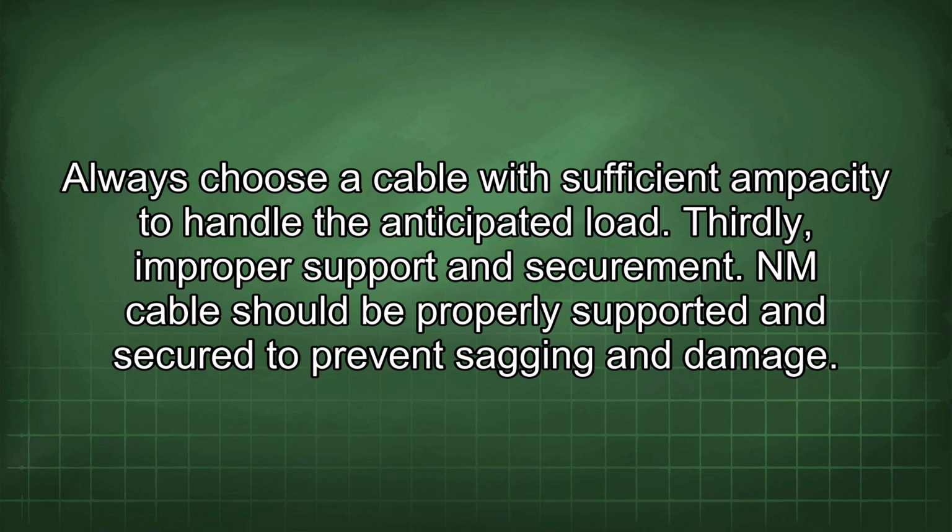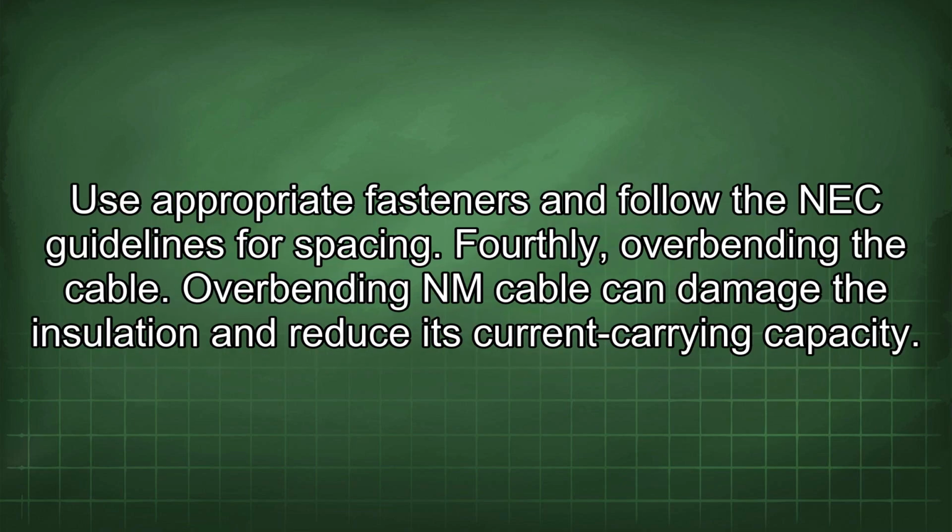Thirdly, improper support and securement. An NM cable should be properly supported and secured to prevent sagging and damage. Use appropriate fasteners and follow the NEC guidelines for spacing.